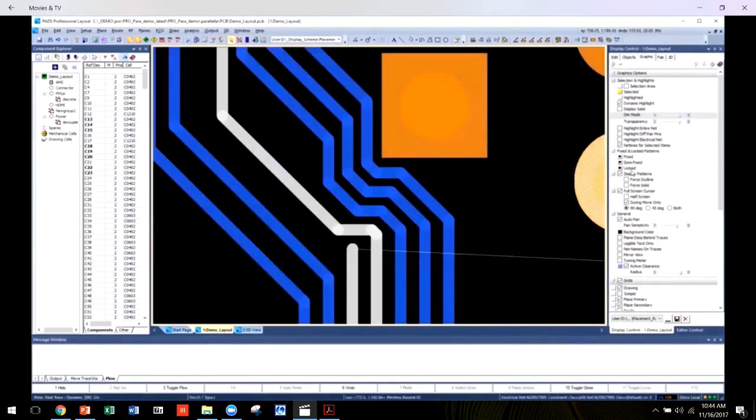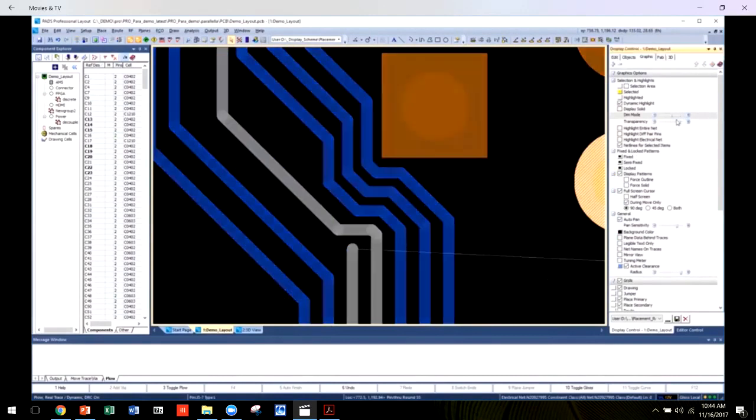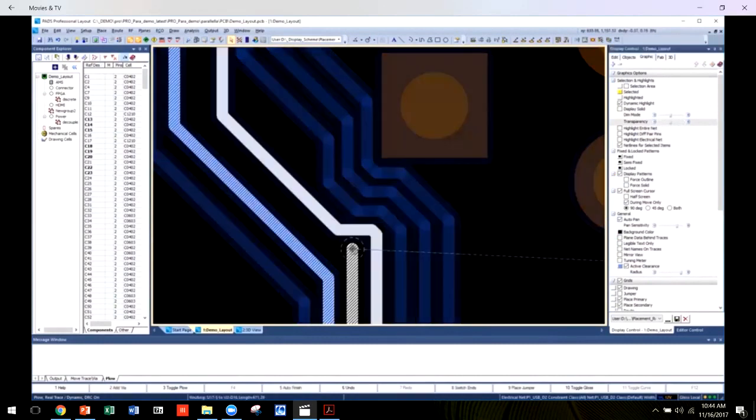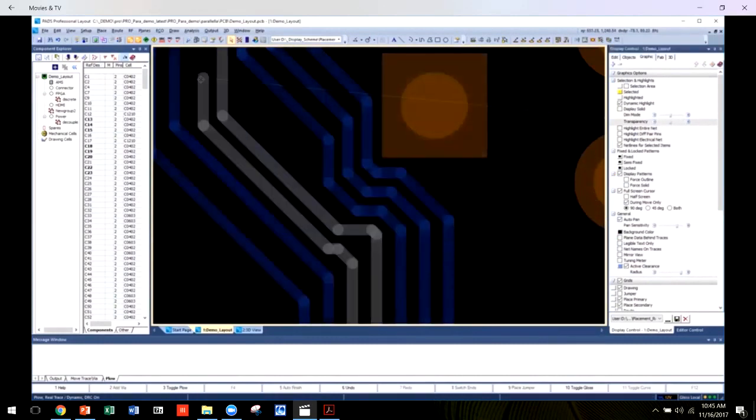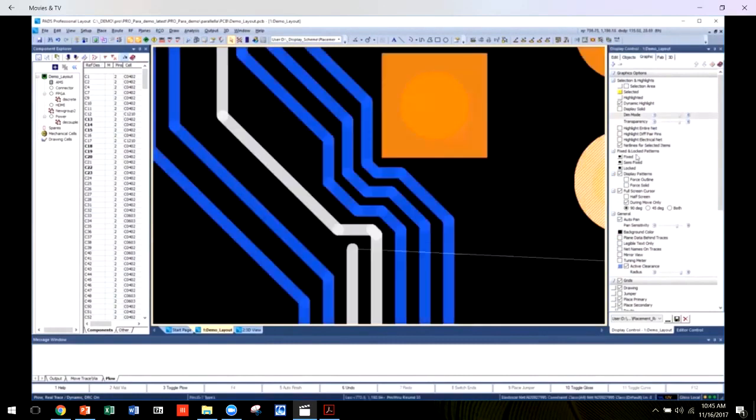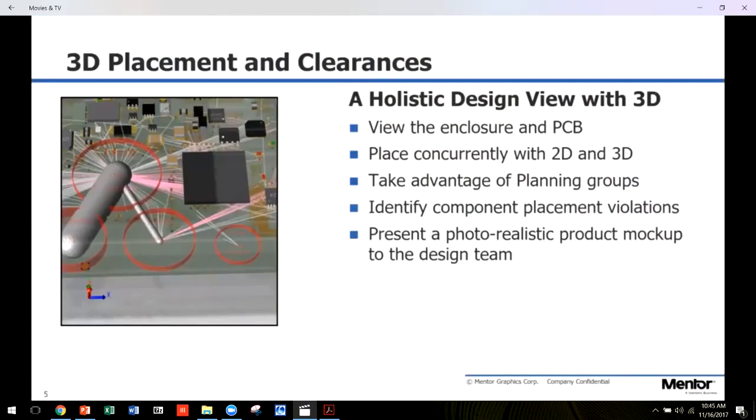Dim transparency mode allows you to graphically control dimming and transparency intensities on unselected, unhighlighted objects, while displaying all selected and highlighted objects at full brightness. These modes are especially helpful in tracking down the physical topology of a trace when cross-probing through a very dense area of the board. No longer do you need to disperse components at the board edge and drag them on.